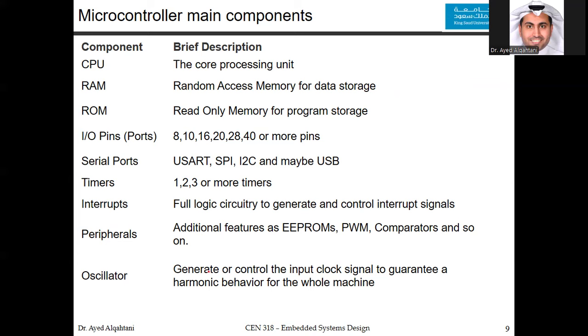The oscillator generates or controls the input clock, which is the beating heart of the microcontroller, to guarantee a harmonic behavior for the whole machine, which will be a synchronized sequential circuit, if you look at it in general.